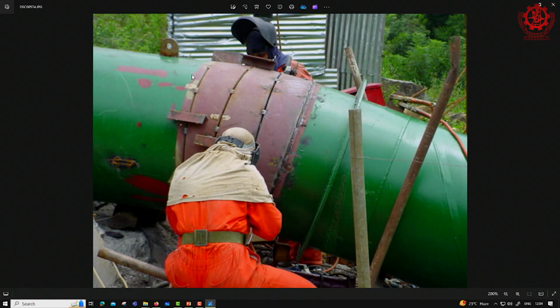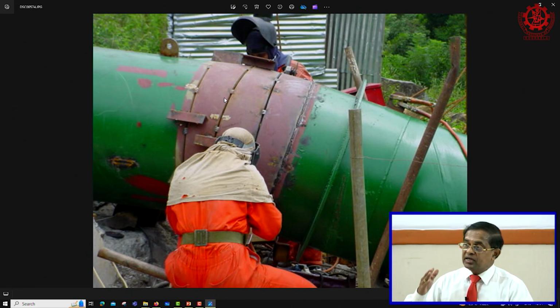They are welding, you can see how a bend is welded. They first tack the pieces together. These pieces we got from the pipe manufacturer himself. We gave the specification for the pipe pieces to be cut into certain angles, as required, so that we can make the bends. He is an X-ray quality welder, and both of them are. They weld from this side and maybe they go inside and weld inside also.